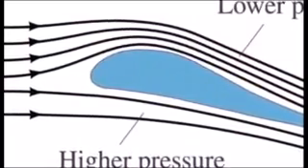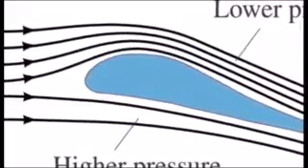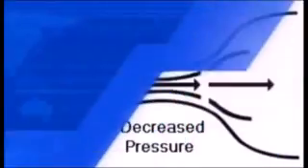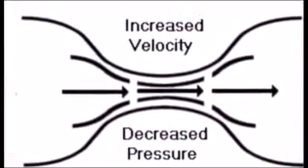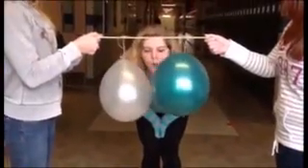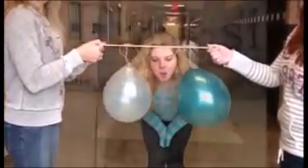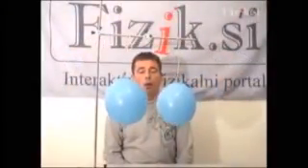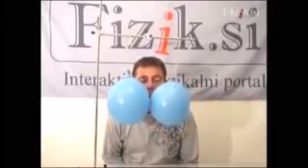Bernoulli's principle states that a stream of faster-moving fluid has lower pressure than the slower-moving fluid around it. As the fluid speeds up, particles spread out, resulting in fewer collisions and less pressure. With the balloons originally hung approximately 5 inches apart, when you blow the low-pressure, high-speed stream of air into the higher-pressure atmosphere, it causes the balloons to constrict into the low-pressure region.